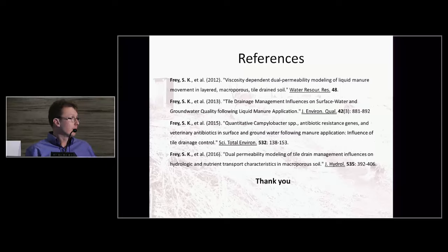The one thing, I didn't really go into a lot of details here about what the hydraulic gradients were under the precipitation events, but when we have rain at this site and we're blocking the drains, the water table gets very close to ground surface, and under that transient response of the system, we drive more of the solutes down into the groundwater under controlled drainage. So there's definitely a more rapid movement of solutes into groundwater under the precipitation events when we're blocking the tiles. And I think that might have had something to do with the higher nitrate levels as well.